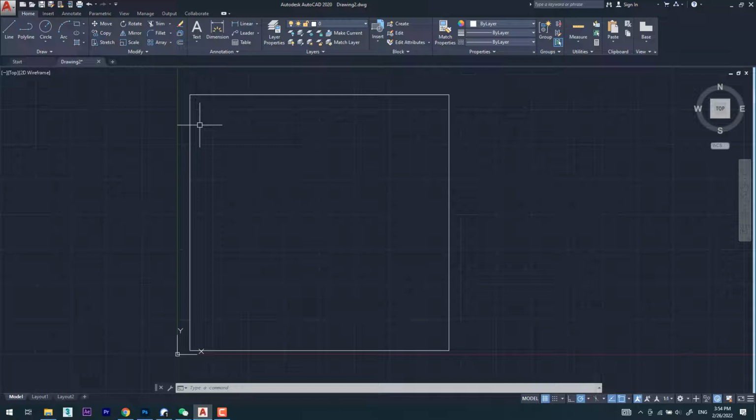So for example, this is the line, and this is the thickness, which is almost 1.5 inches. I want to copy this line by 1.5 inches, so I call offset. I'm offsetting this line by 1.5 inches. This is the line I'm copying, up to there.